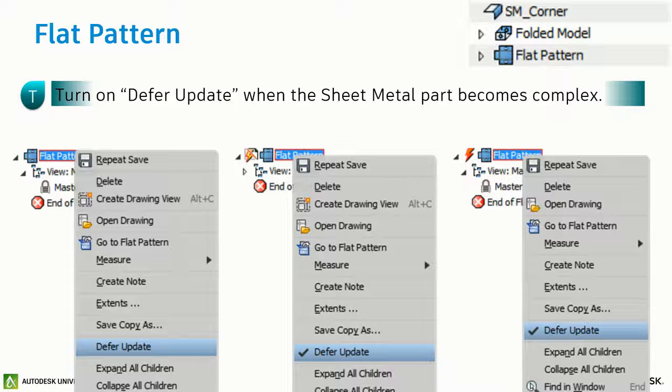Yeah, just one comment. Okay. If you open the sheet metal part, you can select this option from open file data. So we have a complex sheet metal part with flat pattern. We can turn on this option in open file data and open. Maybe the performance should be better. Okay, good comments. So it's easy if you open a large sheet metal design, you can make it quicker from the very beginning.